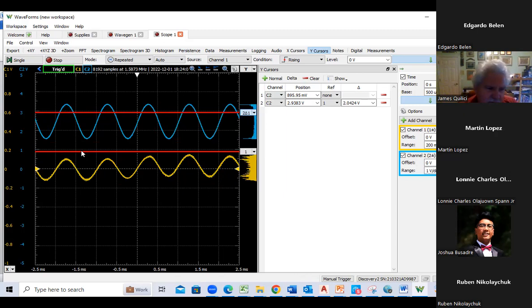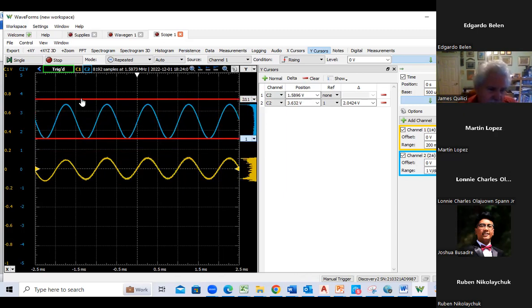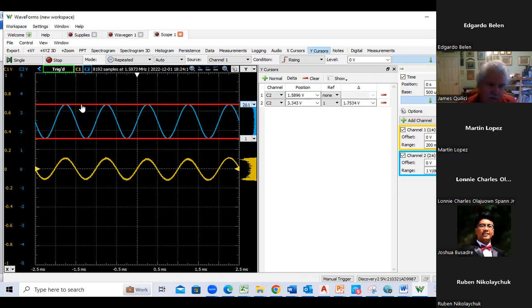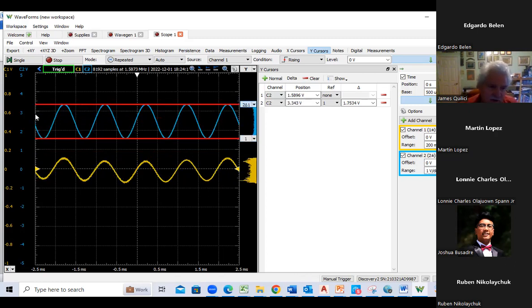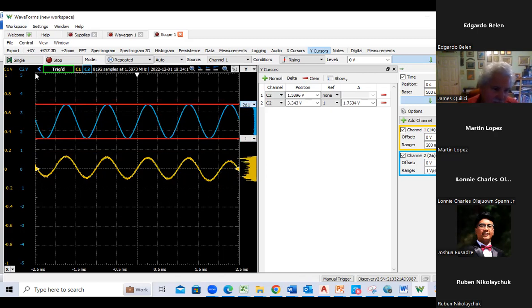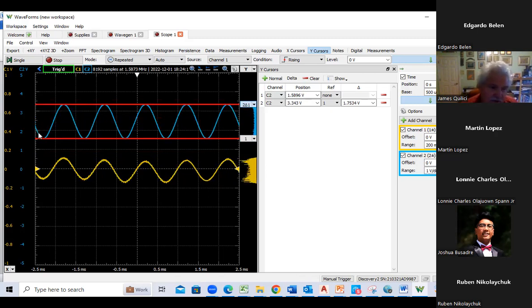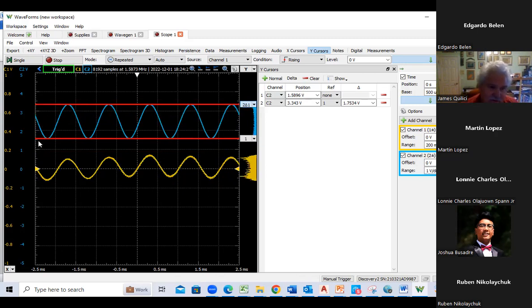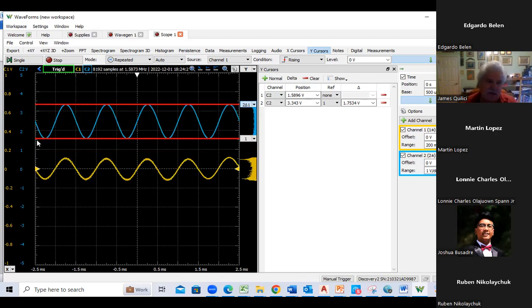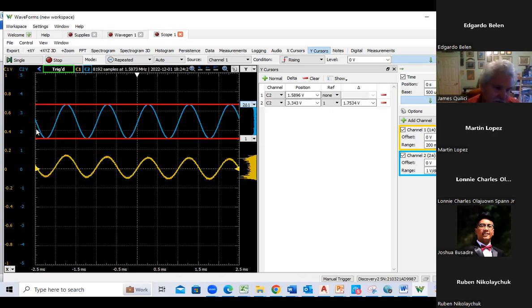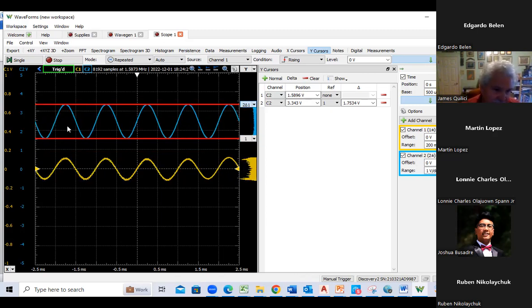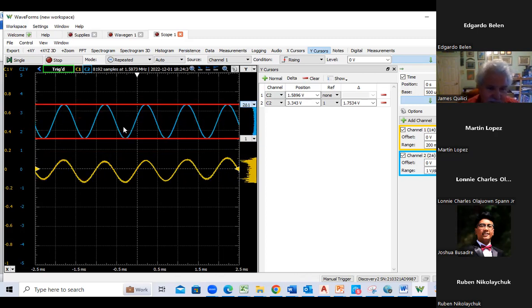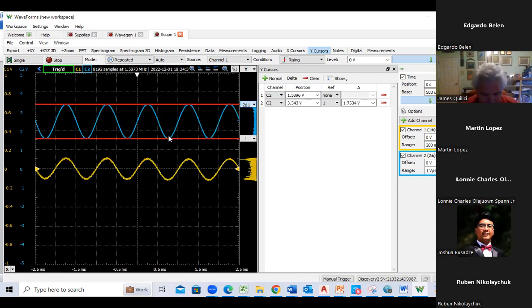So what I did is I reduced my collector voltage, and in doing so, again, it's the collector current: the supply voltage minus the collector current times the collector resistor determines where the collector voltage is. So I was sitting down there at 2, and I reduced it from 2K to 1.5K. Now it's looking pretty good. It's oscillating around 2.5, which is a good spot to be.